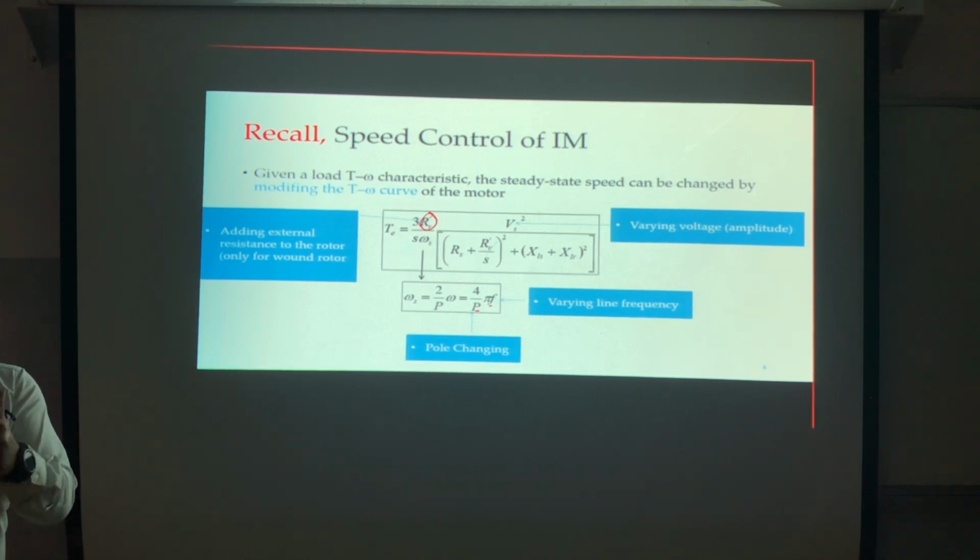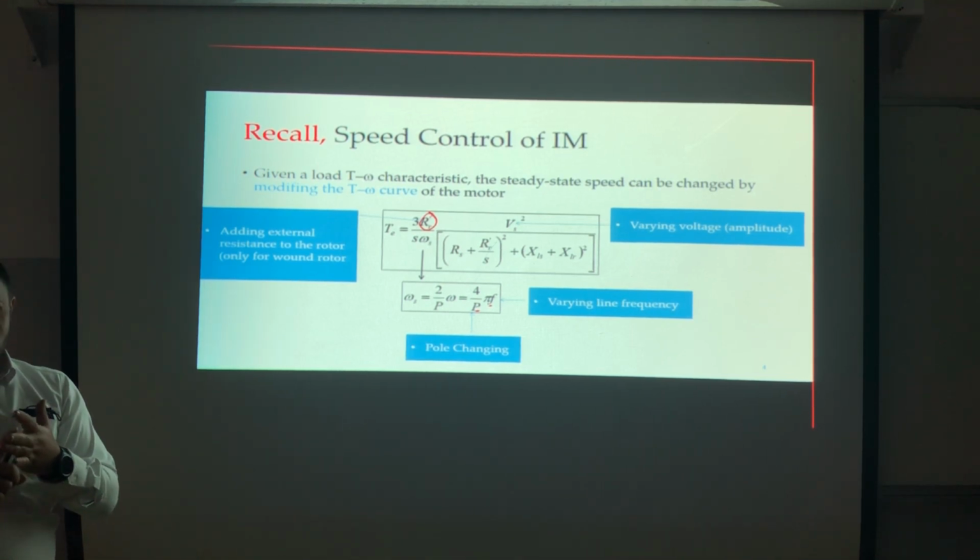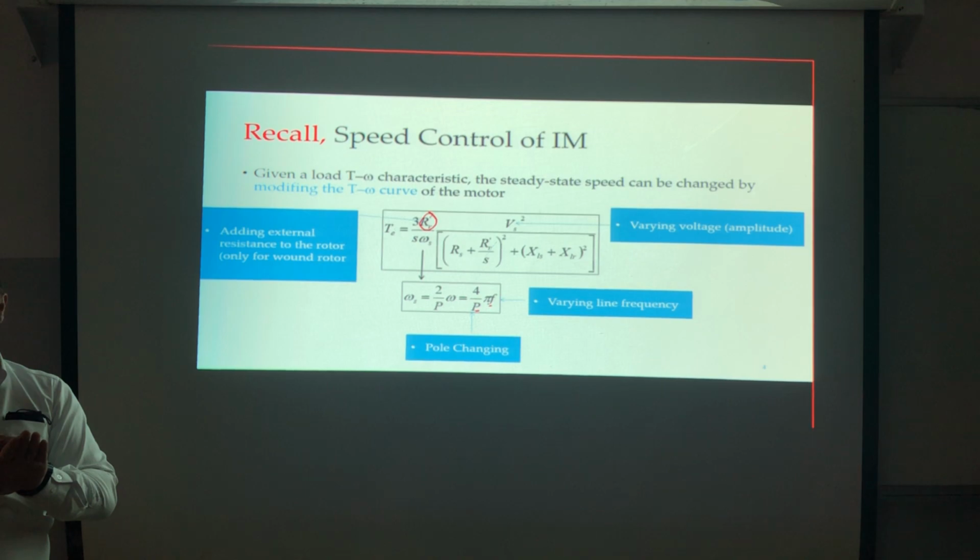Okay. Now, the inverter. If we recall from the power electronics, I need a pulse width modulation, or let's say a gating, in order to convert the DC power to the AC power, correct? Now, in the power electronics, which method did you study? Bipolar PWM, unipolar PWM. I think you studied the pulse width modulation and the 120 degree and 180 degree, correct? So those can change the frequency, depending on the reference, correct?